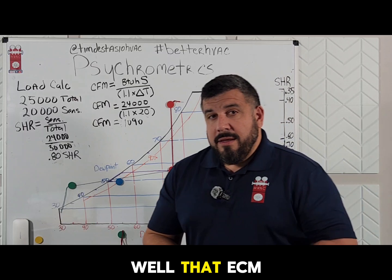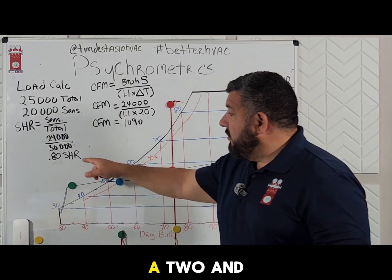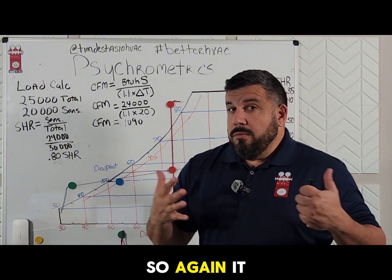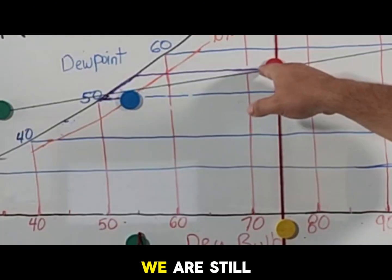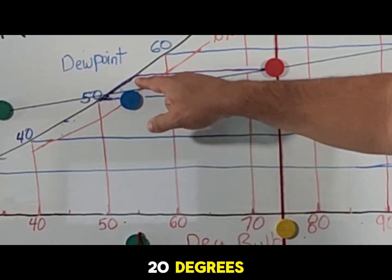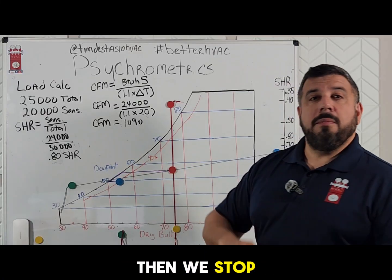Well, that ECM motor, if we tell it to do 1,090 CFM on a 2.5 ton unit, we probably can make it do that. So again, it doesn't look like we're going to have a problem, but notice what happens with only that 20 degree temperature drop. We are still cooling the air, and then when we hit 20 degrees, we barely make it to the saturation curve, and then we stop cooling.